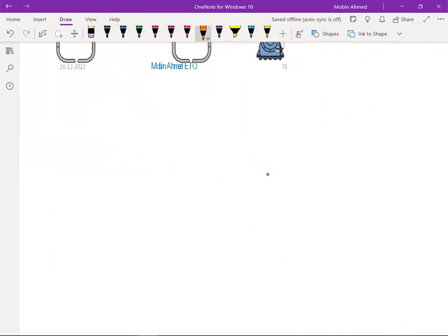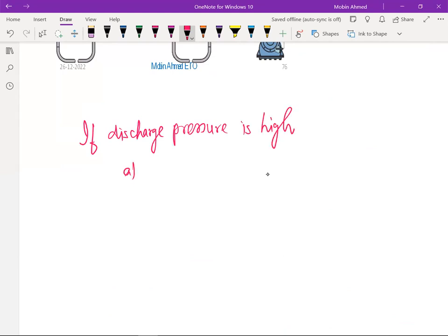If discharge pressure is high, there can be many reasons, but the most common is that your cooling water flow is less or the temperature is high.